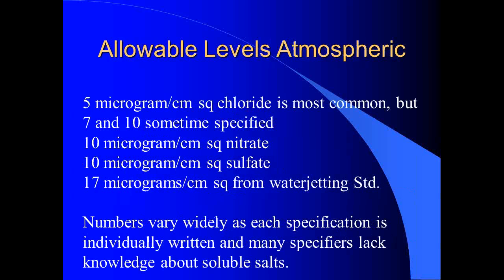And atmospheric levels. 5 micrograms per square centimeter of chloride is the most common. Some DOTs and such are using 7. Some other specifiers are allowing 10 of chloride. 10 micrograms of nitrate and 10 micrograms of sulfate is pretty normal on bridges and structural steel.